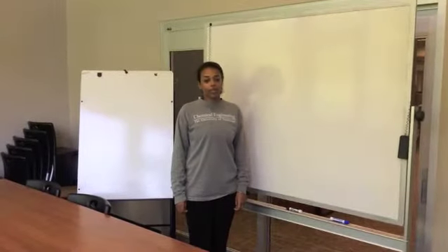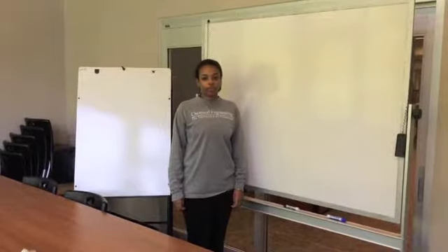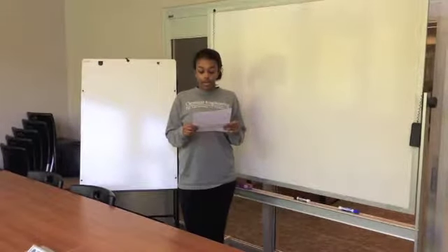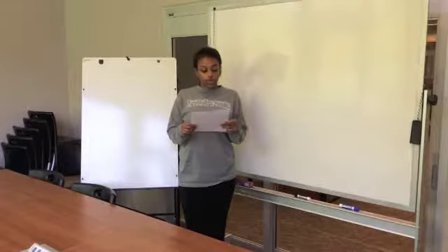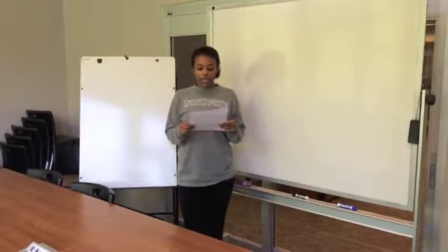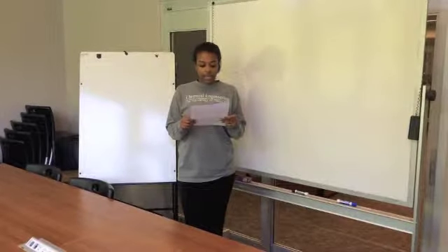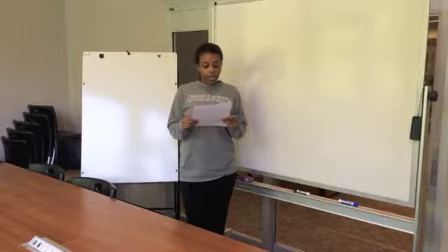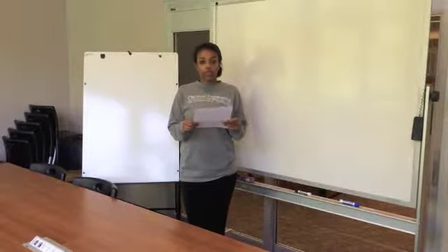La. I'm Lina and we will be working out a fluid flow problem for you guys. Problem states, water having a density of 1,000 kilograms per meter cubed is flowing at a rate of 1.85 meters per second in a 3.068 inch diameter horizontal pipe. At a pressure of 68.9 kilopascals, it then passes to a pipe having an inside diameter of 2.067 inches. Part A states, calculate the new pressure in a 2.067 inch pipe, assuming no friction loss.